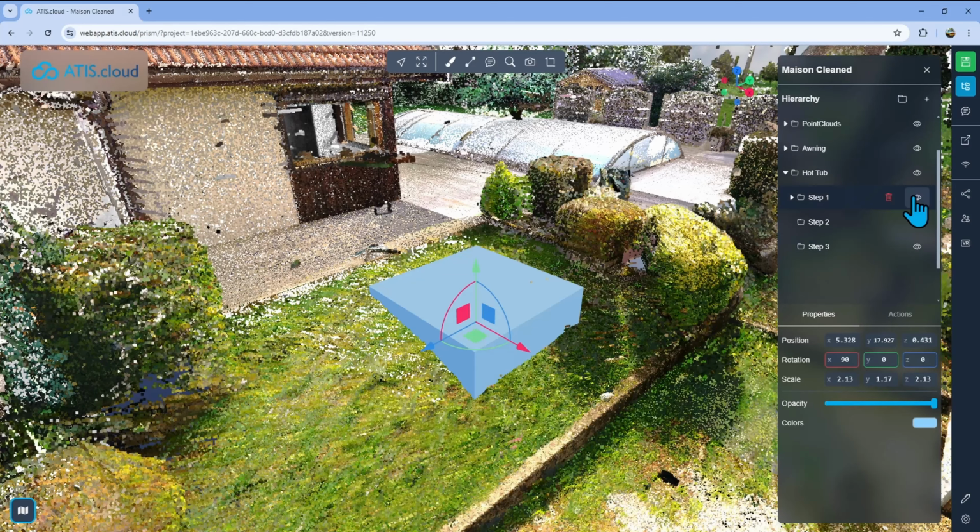So now I have it aligned here at the front, but I don't have it aligned here on the side. So what I'll do is take it, move it just a wee bit here so that it's aligned on that side. I don't care that it's not aligned here behind because it's actually terrace on terrace, so it doesn't really matter. What I will have to do, however, is create a clipping box to hide it over here.